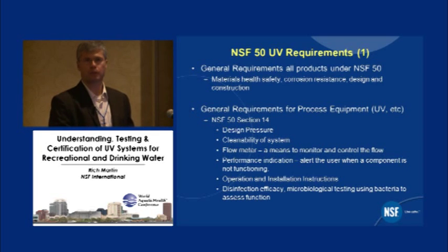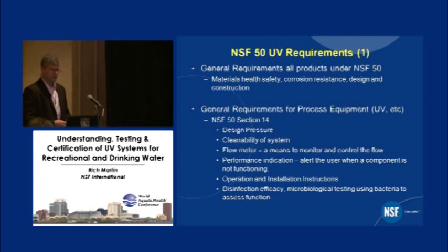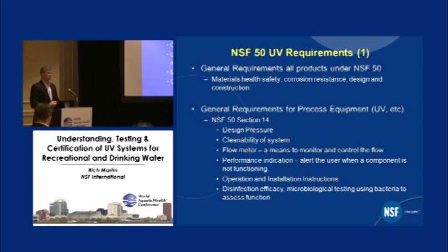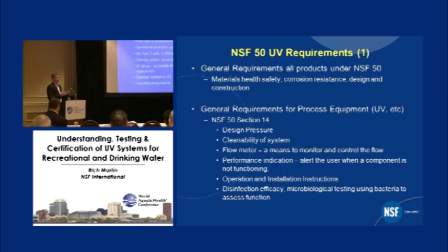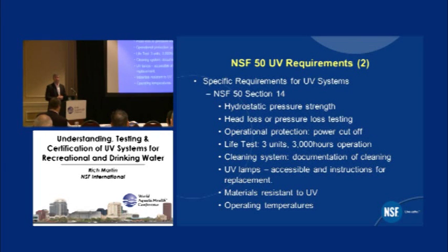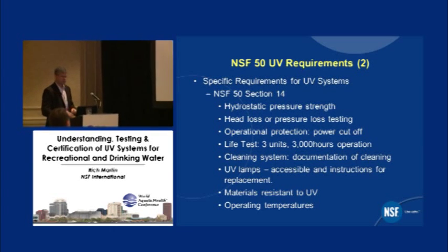But beyond that, we also have requirements for the operational instructions, the installation instructions. Really very common sense things that should be in there are called out and specified in the standard. Some of these criteria are more on what I would consider the actual testing criteria, not just documentation. So some of those criteria are the burst pressure strength, so it's really taking your manufacturer's claim for the safe working conditions and then doing a multiplier to get a higher burst pressure safety confirmation.